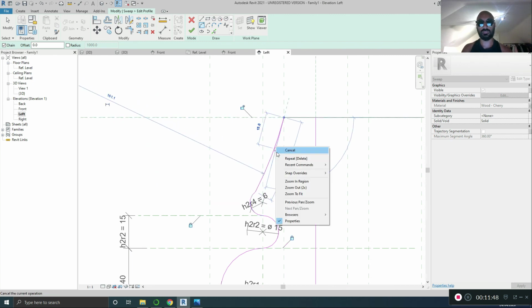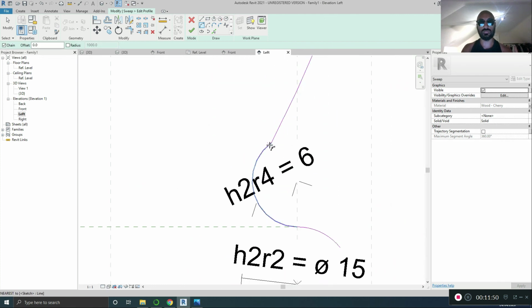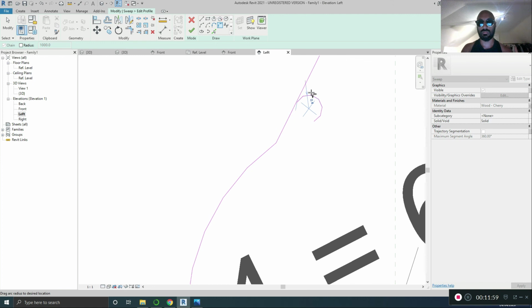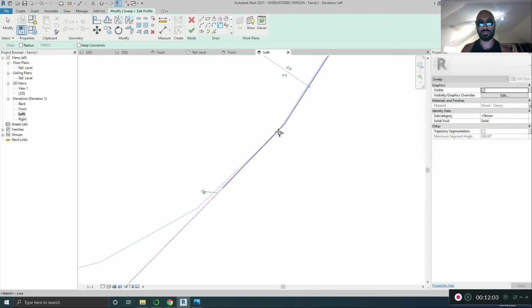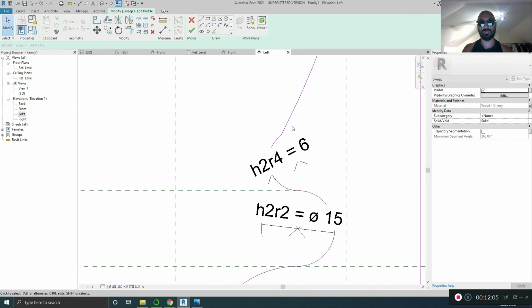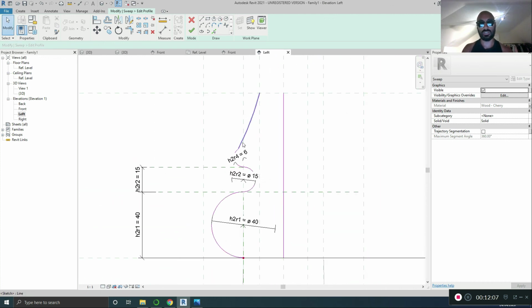Come here like this. This is what I was going to talk about earlier, actually. This is what I wanted. The curve to come that way. And then I can fillet the arc there to there. If you go like that, it's a mistake. You need to make sure it's down here. Sometimes it may be too small to see. Don't dimension these, they're fine. So, pick lines, that, trim.